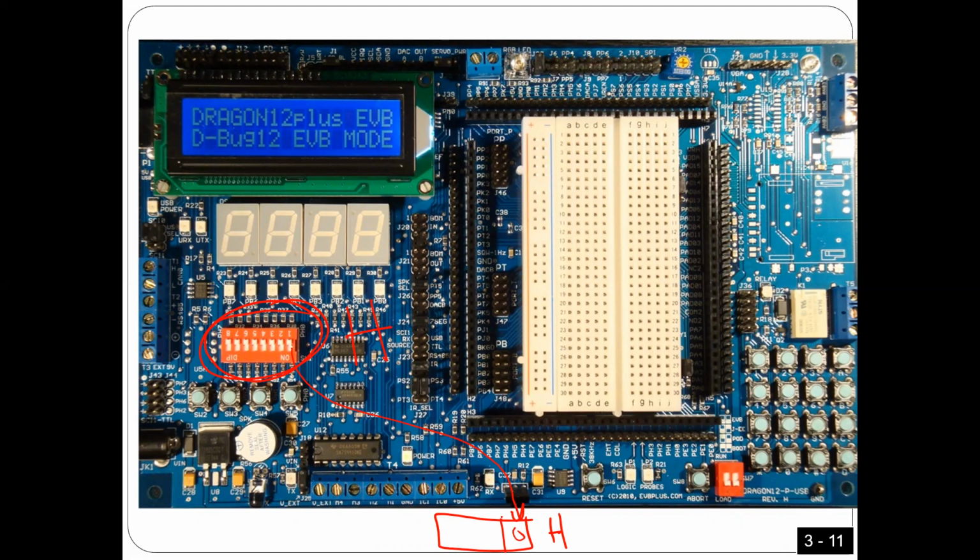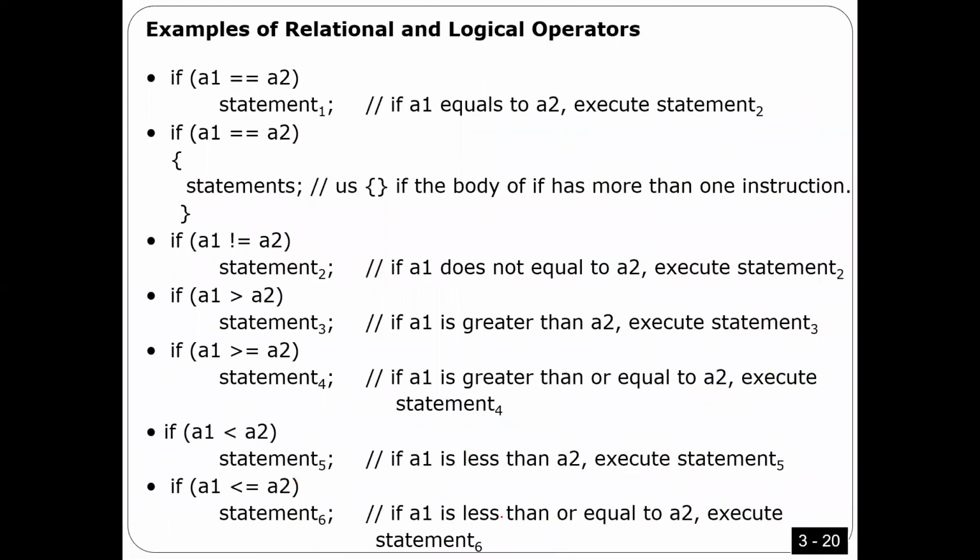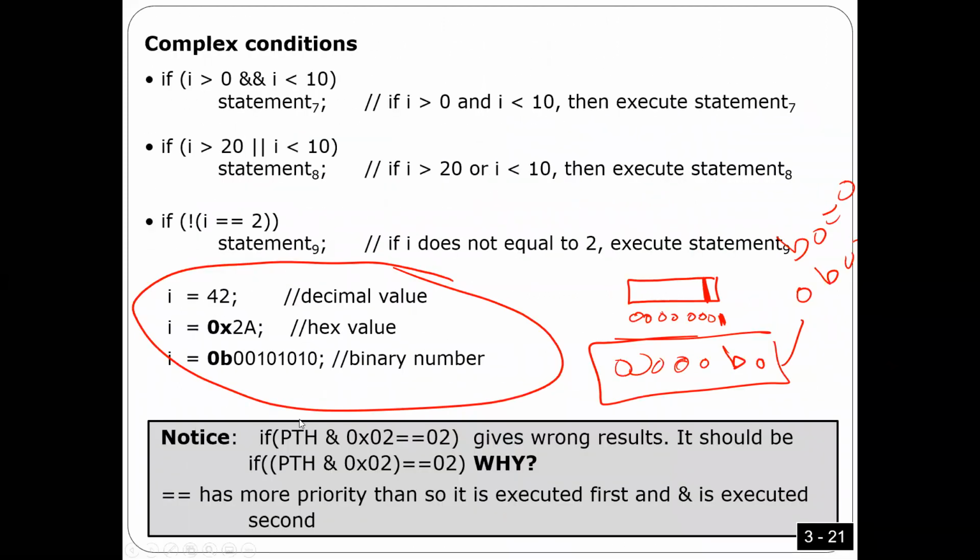So if you want to know if a switch is connected or not, all you have to do is read port H, which is a byte, and then check the bits corresponding to the switch you want to check, okay? So, now how can we do it? I can do something like that, and that's wrong. Let me explain it first, because this is somehow weird, okay?